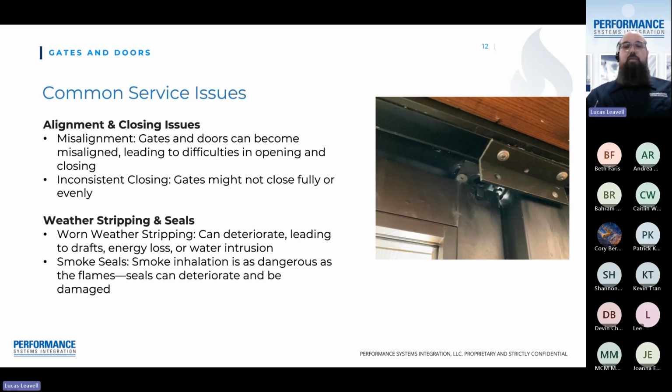After mechanical problems, the next most common issue you're going to encounter is alignment related, especially with metal. Anything made of metal can and will warp when impacted. As pictured here, this is an aluminum door. This door is no longer going to be able to latch and close properly because it is bent. Now the glass may have survived, luckily enough, but the frame is bent, or the door itself and the frame around it are now bent from an impact on the outside.